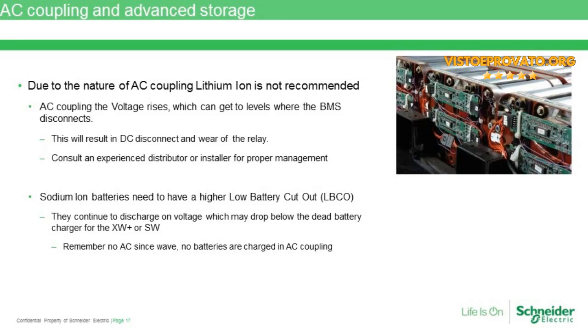So the customer's chosen something that is going to be normally selling power back to the grid. And so when speaking with the customer about how often they're losing power, this may be a really important question at the end of the day, simply because most of the time when we're sizing out batteries, we size for 50% depth of discharge, or if it's self-consumption, it may be 25% depth of discharge.